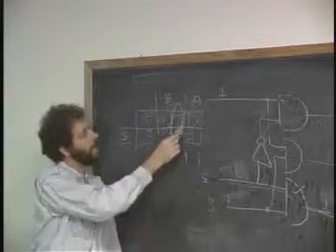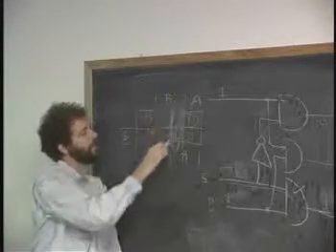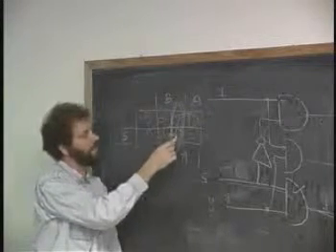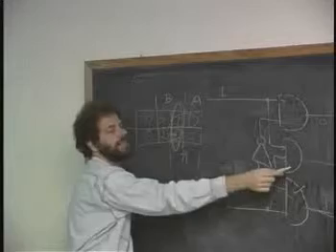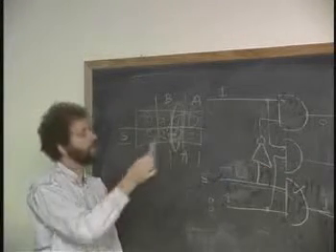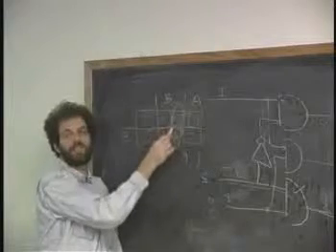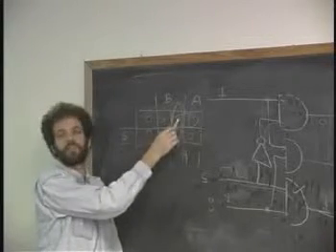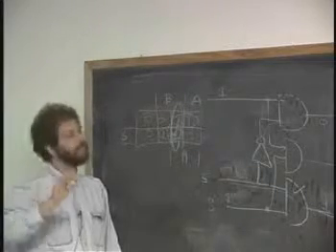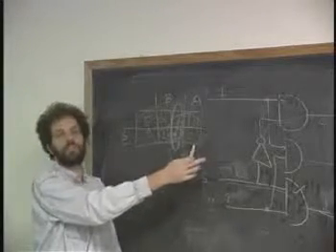So I fixed the problem by adding another island here, which doesn't care about S. And so when I transit from this state to that state, this middle gate isn't even looking at S. And so it is responsible, and it holds the output up irrespective of the transition that's happening here. And I can take forever to make this switch. It can be a very slow slope. It can oscillate up and down. Doesn't matter. The wire doesn't even go to the gate.